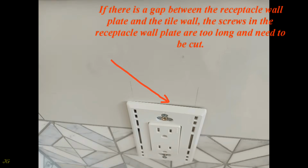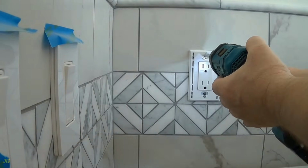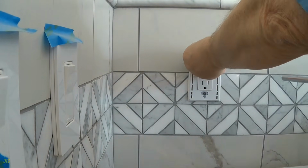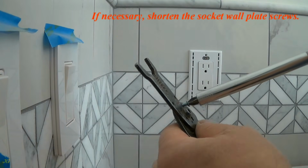If there is a gap between the receptacle wall plate and the tile wall, the screws in the receptacle wall plate are too long and need to be cut. There must be enough space behind the receptacle yoke for the longer receptacle wall plate screws. There is no slot in the wall tile for the receptacle wall plate screws. If necessary, shorten the receptacle wall plate screws.